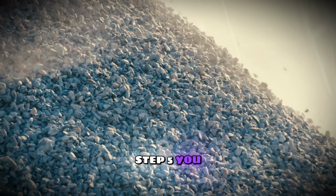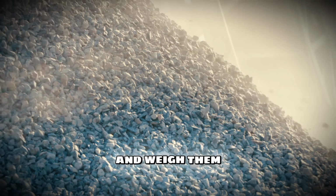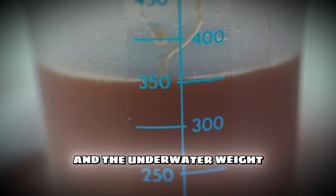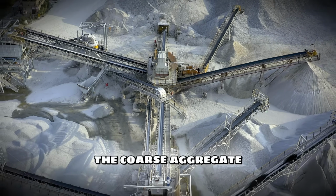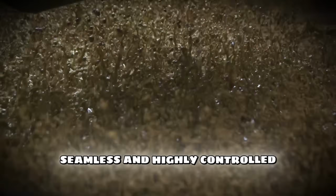Step 5. You take the rocks out, dry them completely in an oven overnight, and weigh them one final time to get the absolute dry weight. By comparing the dry weight, the saturated weight, and the underwater weight, you can determine not just the specific gravity, but also the absorption rate of the coarse aggregate. The bench makes handling these heavy, wet samples entirely seamless and highly controlled.